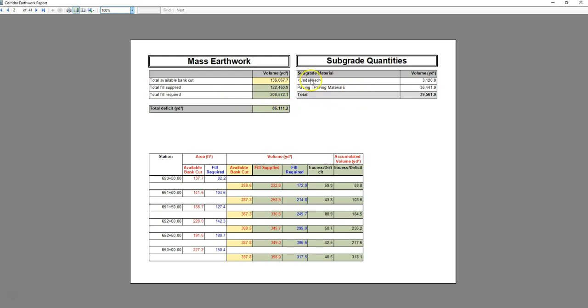And then over here, subgrade, you can see where I didn't put in the paving materials. So for paving materials, there's a couple that I missed that are undefined. That's why it's broken out. But it should only show you one if you define them all as one. If you break it out and define it as your asphalt, your gravel, your concrete, depending on what you're showing, it's there.